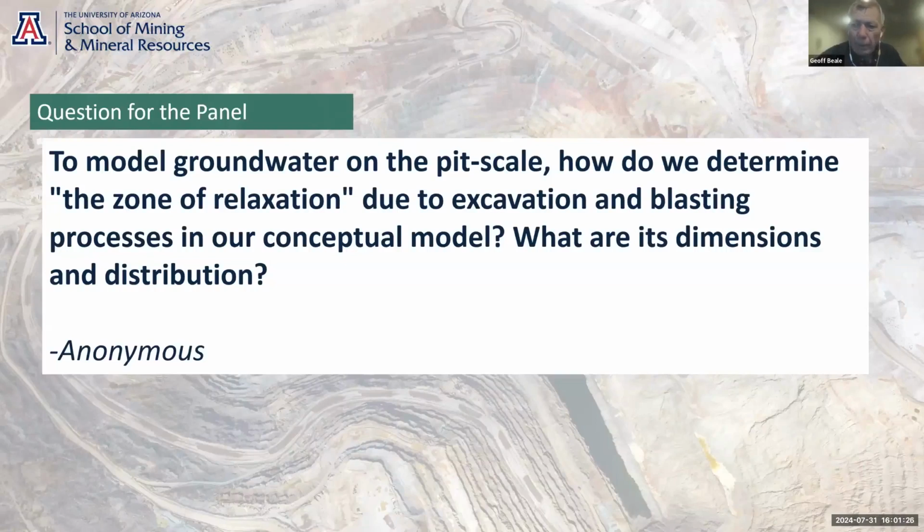And if you get, as Jeremy says, if you see the piezometers drop when you mine, then the slope is dilating, and you're within the zone of relaxation. But extremely difficult. So first thing again is to probably look at the piezometers. Lauren, you've got a fair bit of experience on this. Yeah, I was going to say exactly the same thing, that piezometers are the first choice.